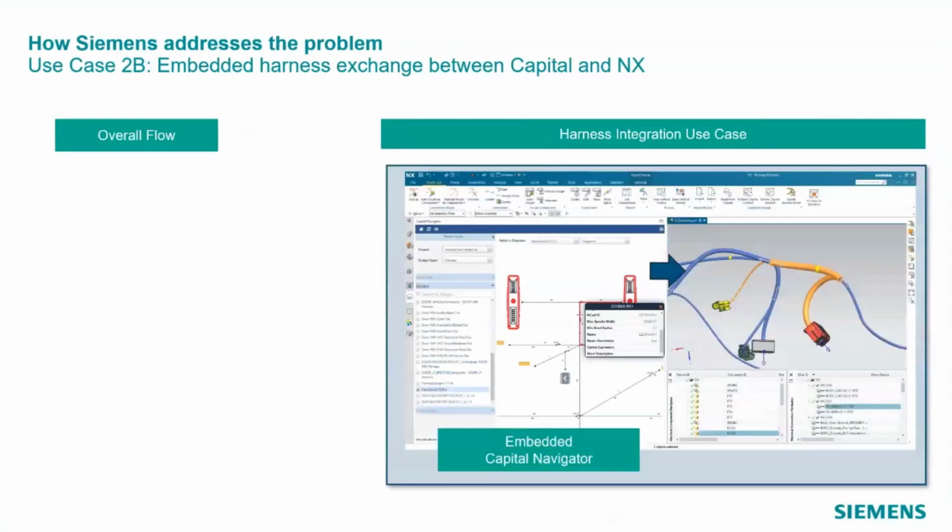In many companies, NX has been used as the container for electrical data, even though it is not an electrical design tool. This can cause excessive design sizes as the wiring connection data has to be fully implemented and saved in the NX model. In some cases, this leads companies to split the harness across zones to manage the data sizes. To address this issue, we have introduced the ability for NX to contain only the harness structure and connectors and to visualize the wires defined in the electrical model in the context of the NX harness.